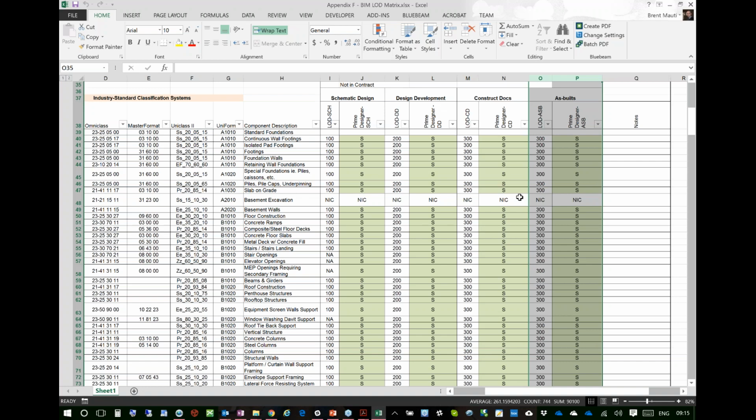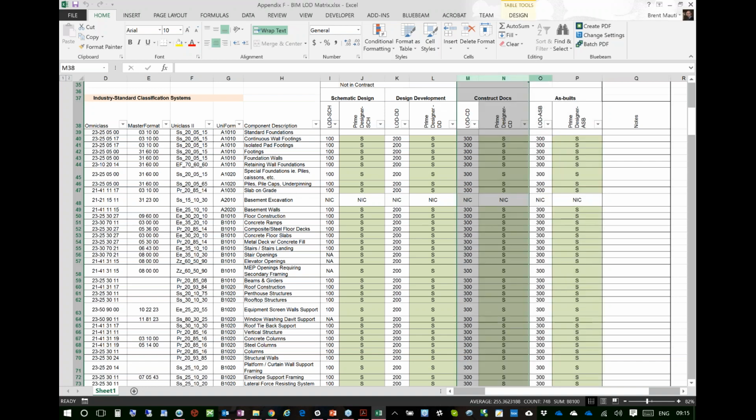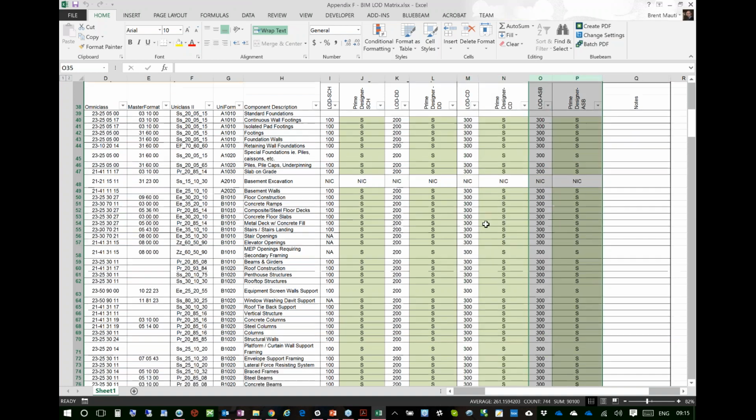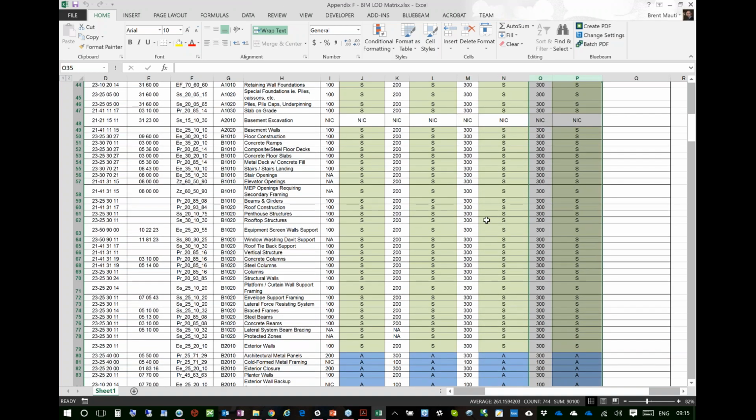As-built or record model basically means we take our design models and we update them to the as-built condition. We don't update it to make it developed as constructed. The example there is you have a beam going into a column, and maybe the beam became 5 inches deeper. Well, we make the beam deeper in the model.